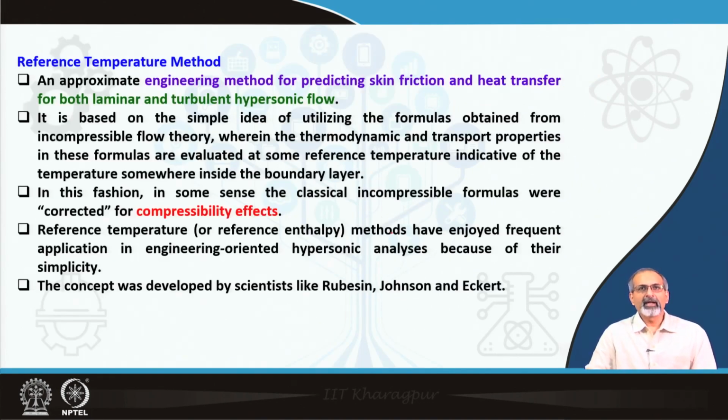And based on that, we come to the concept of reference temperature method, where we say in the beginning that it is an approximate engineering method for predicting skin friction and heat transfer for both laminar and turbulent hypersonic flow.